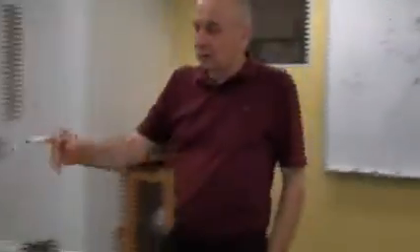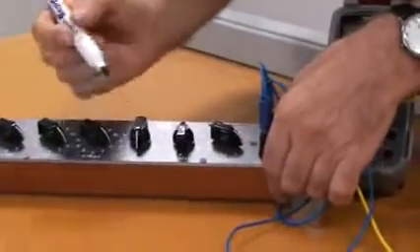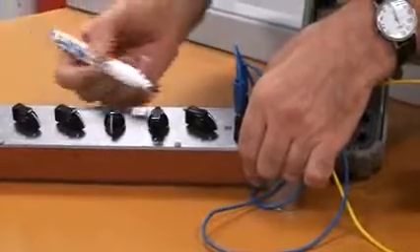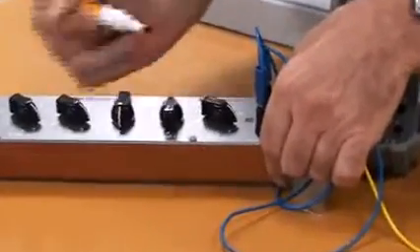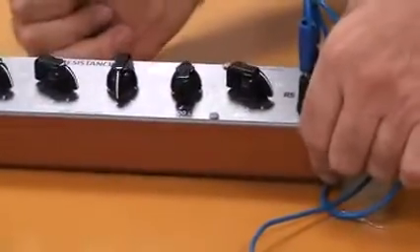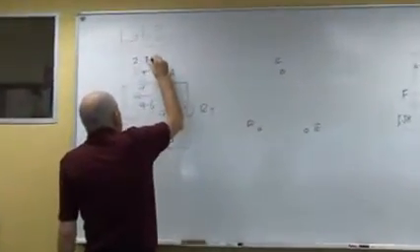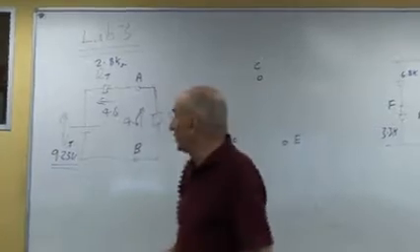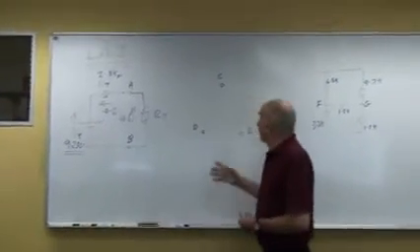If we read off that resistance there, we know the value of RT, and it's going to be 2,800 ohms. 28 ohms. See? 2 times 1K, 8 times 100. So, RT for this box is 2.8 kiloohms. And that's the result. And that's the end of part A. We've now finished part A of the experiment, the Thevenin theory part. Now we're going to do part B.